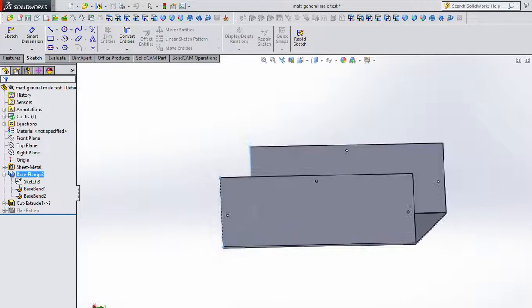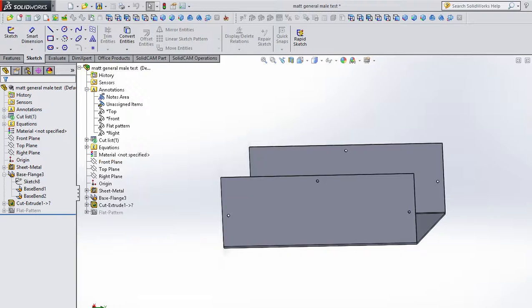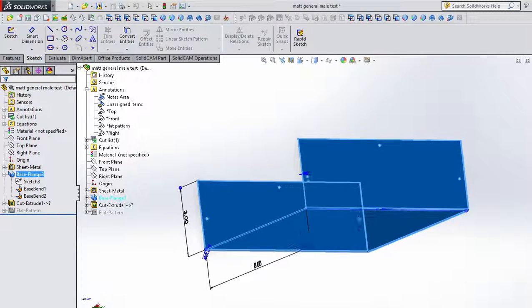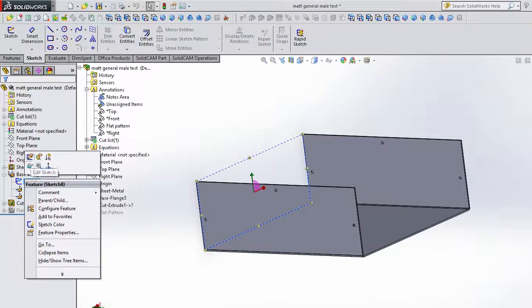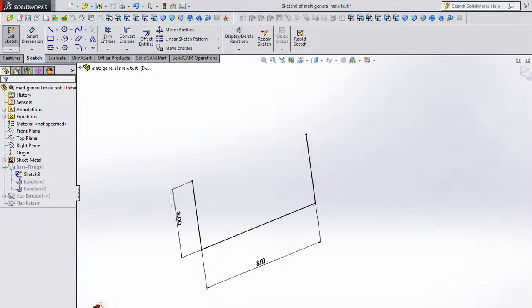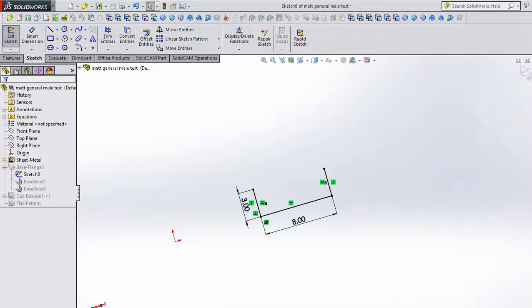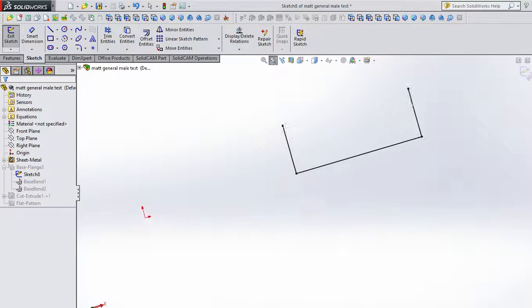In order to do that, you have to do something called building the part off of this part within an assembly. And before I go to that, you're going to run into trouble. I'm going to open the sketch. You are going to run into trouble if you build parts off of assemblies and there isn't a common reference. So for example, look here.